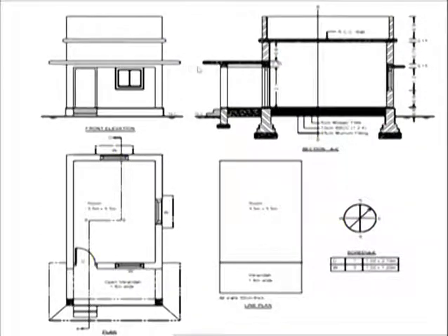So this is the bottom of the lintel, and then the top of the lintel, then the bottom of the slab line, and then the top of the slab line, horizontal lines will be there. After the slab roof, the parapet is provided, and the thickness of the parapet wall will be lesser than the thickness here. So this is the top of the parapet. That horizontal line you can draw.